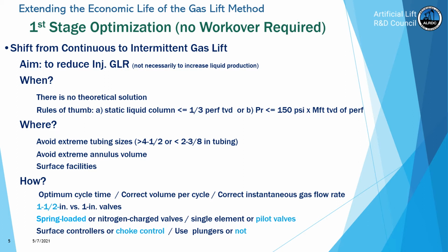Once you know how your valve will behave in a given field, then it should be easy to predict how it will behave and which value of the area ratio you need. For example, if your calculation gives you a certain area ratio, you know that you have to increase that area ratio, maybe going to the next one available, and so on.